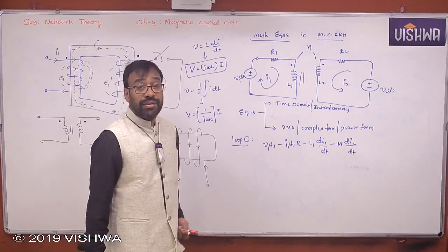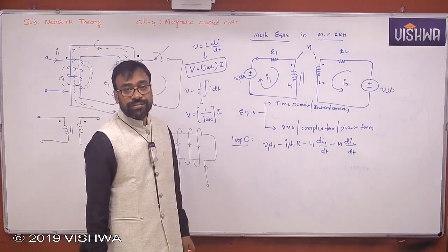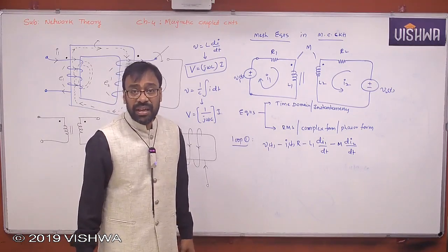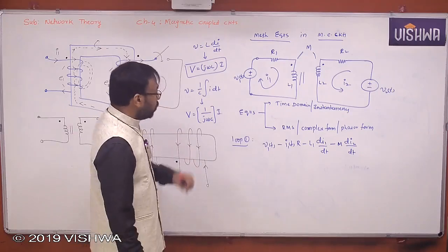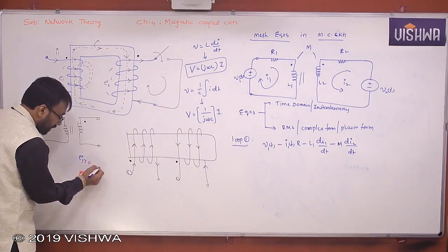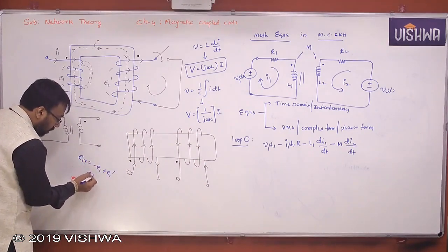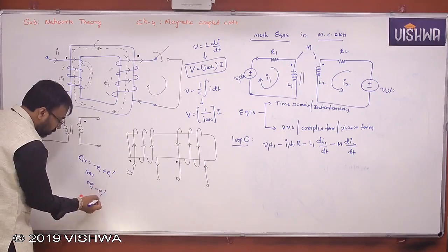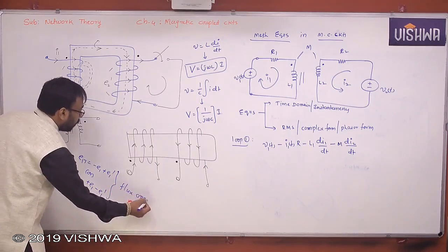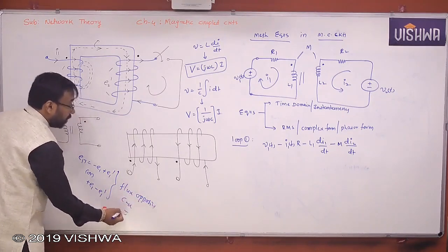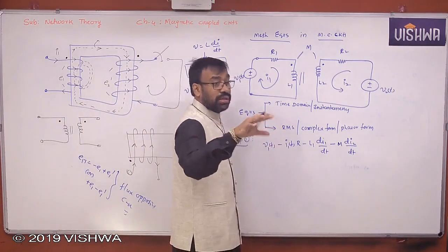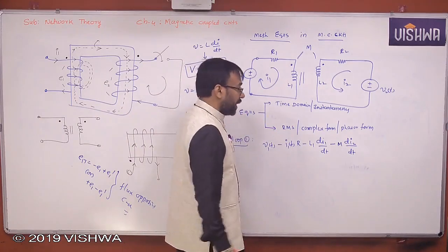Understand all of you? Now tell me, flux aiding case or flux opposing case? Which one are you getting here? You are getting flux aiding. Whereas in case 2, we have already seen that E1 total is minus E1 plus E1 dash, or plus E1 minus E1 dash. In that case, what is happening? Flux opposing case. Yes or no, all of you? If you have written it, okay. Otherwise, write it there itself, where we have indicated the dot convention method, where we have taken two cases.